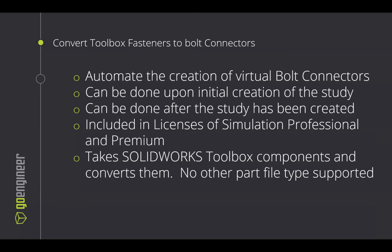There's a little bit of metadata in there specifically for this, and it'll then translate to features in simulation to exclude the fastener from the simulation and add in its place its own dedicated feature with the appropriate preload, shank and nut diameter, etc. This tool is only for Simulation Professional and Premium. But let me show you how to use this tool.